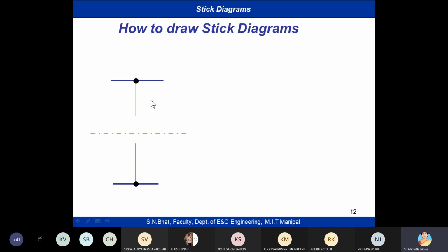Then here you should have a contact for the supply to the P diffusion, and ground to the N diffusion. So provide electrical contact. The black solid dot is the symbol for an electrical contact cut. Whenever we provide a contact cut, after metallization that will provide a contact to the component. This black dot represents a contact cut, so if you provide a contact cut here, it is providing electrical connection.